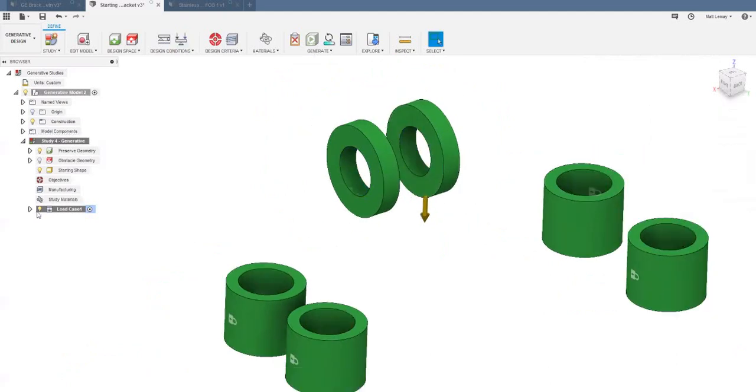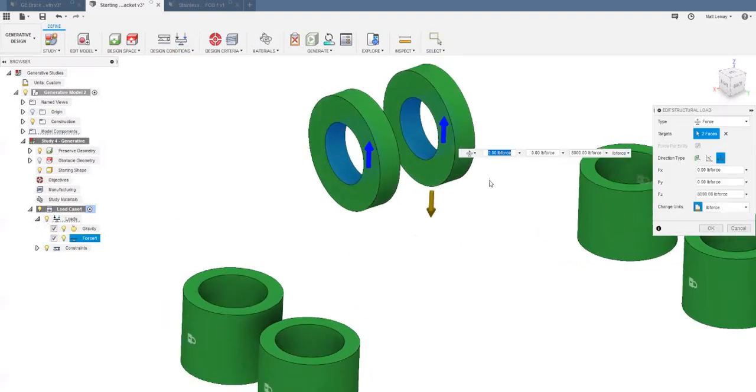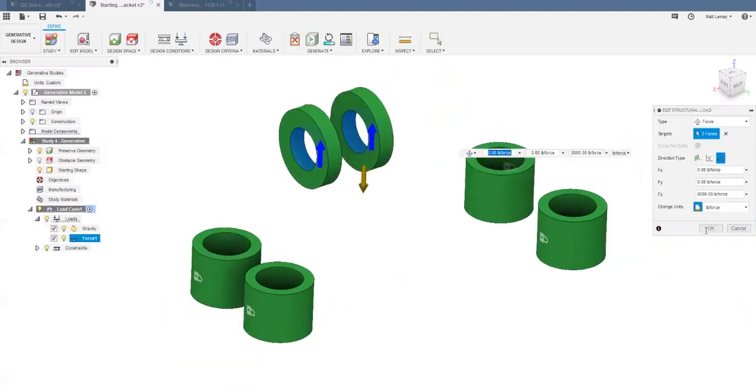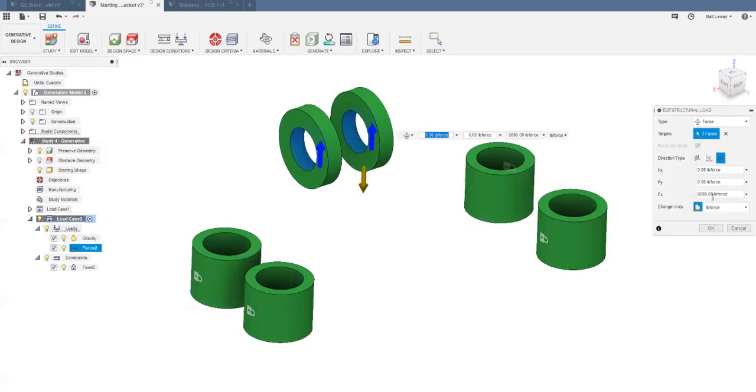And you can see after we've set that, the force arrows are now pointing vertical the way that we'd want. So that's our first loading condition. And to get to our second, to save time, we could right click and clone that load case. And what that's going to do is create this new load case 2, which is bringing everything the same from load case 1. And in this case, rather than resetting up our constraints and our loads, we just need to